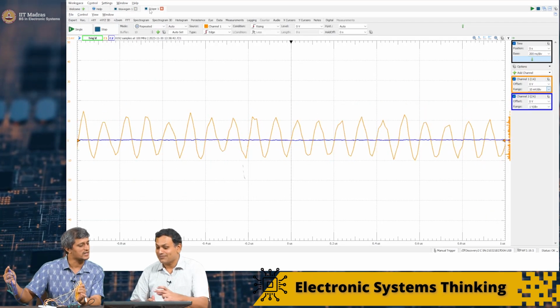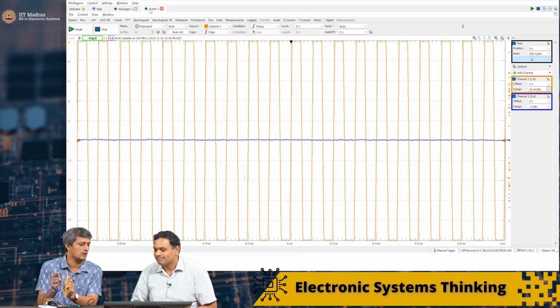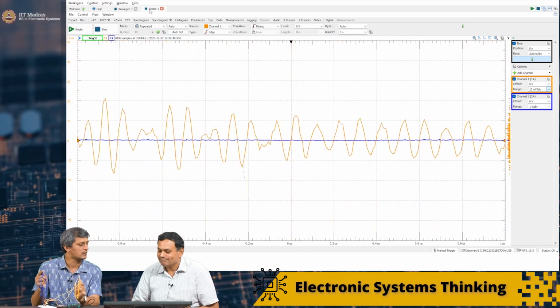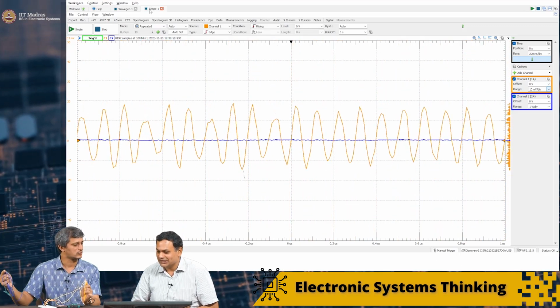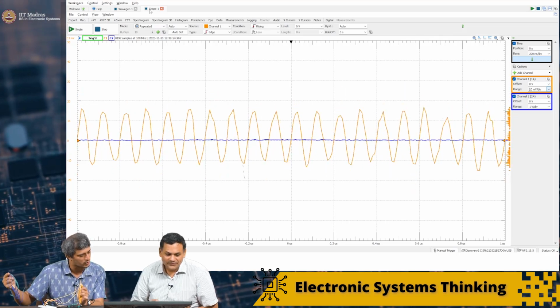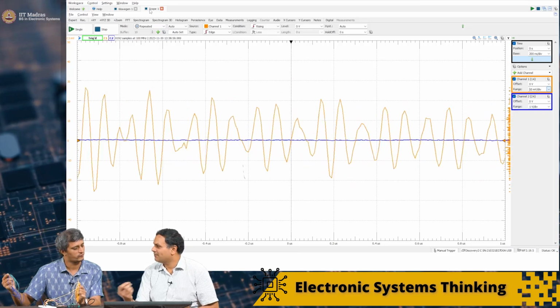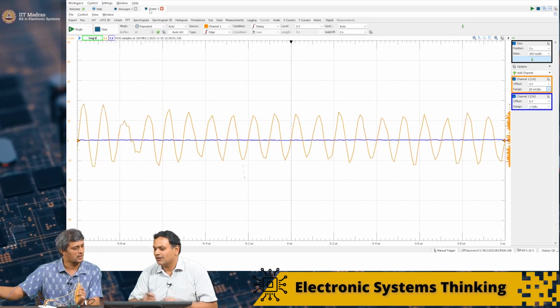You can see it's a much larger amplitude and it's fixed as well. If I bring it close, you see the inductive coupling kicking in. So this is reasonable, like some 40 millivolts? I don't know, it's about 20 millivolts. Whereas the noise that was coming was like 5 millivolts or so. This is about 4, so 3-4 times.